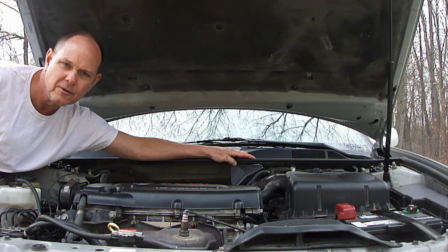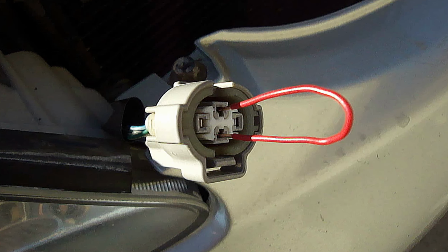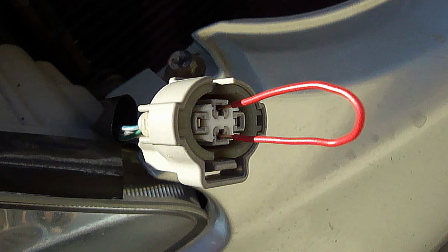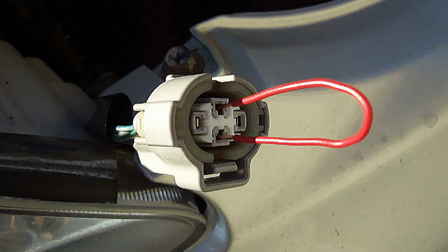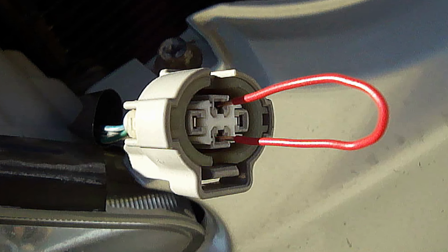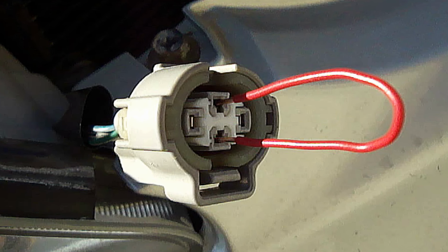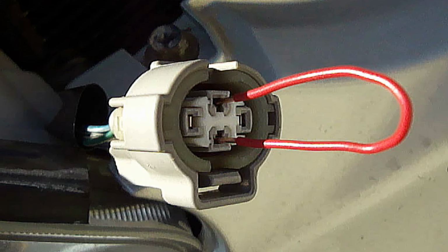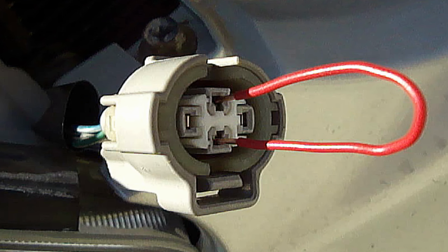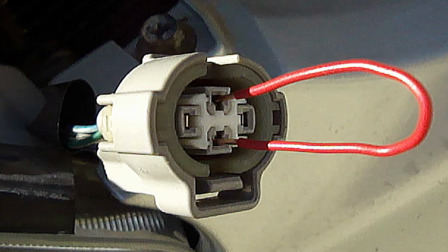The easiest way to test a pressure switch is by performing a test which bypasses the pressure switch. This is a lot easier than trying to test the pressure switch by itself. If the compressor clutch starts turning when the pressure switch is bypassed, then you have a bad pressure switch which needs to be replaced. If you do not replace the pressure switch and leave it bypassed, the compressor will have no protection from the refrigeration pressure being too low or too high.